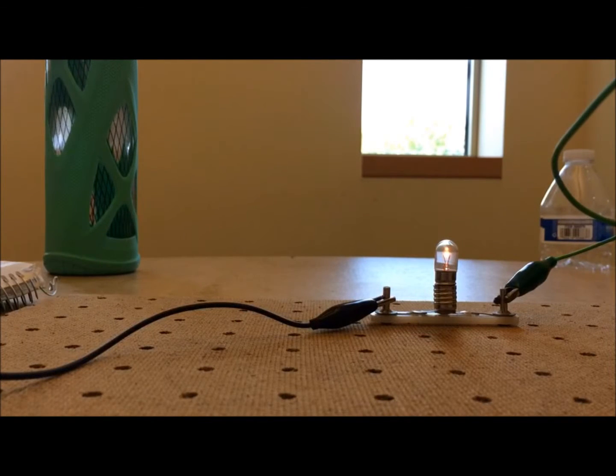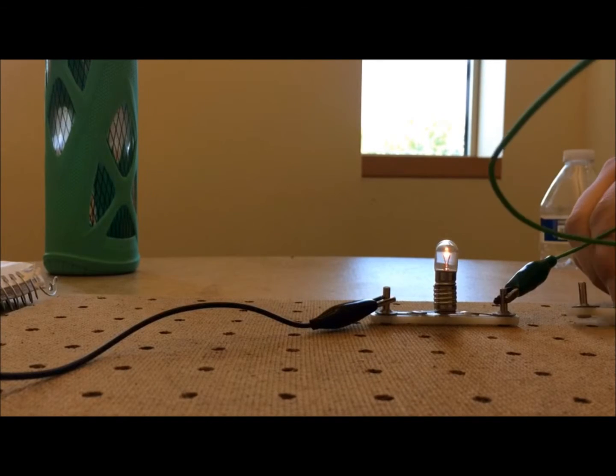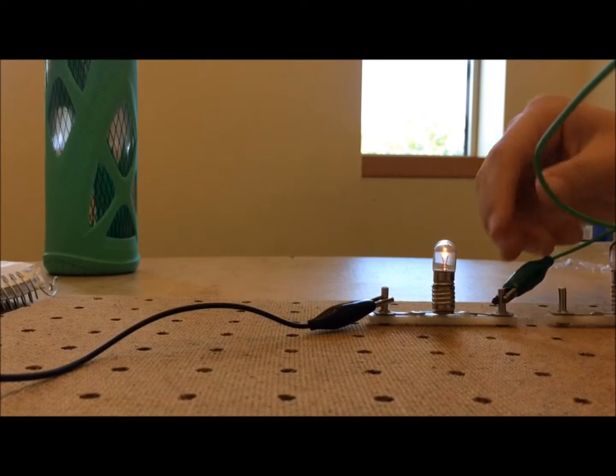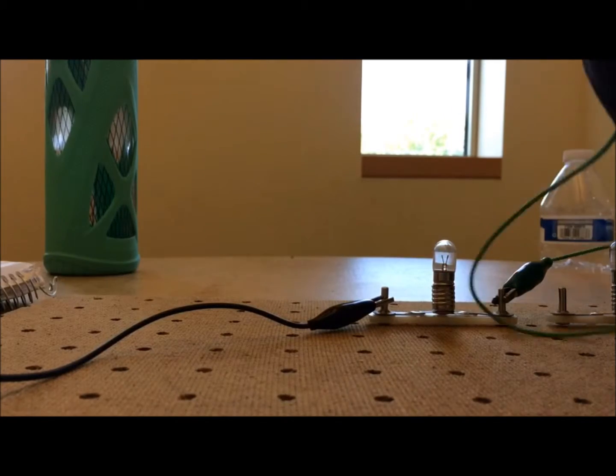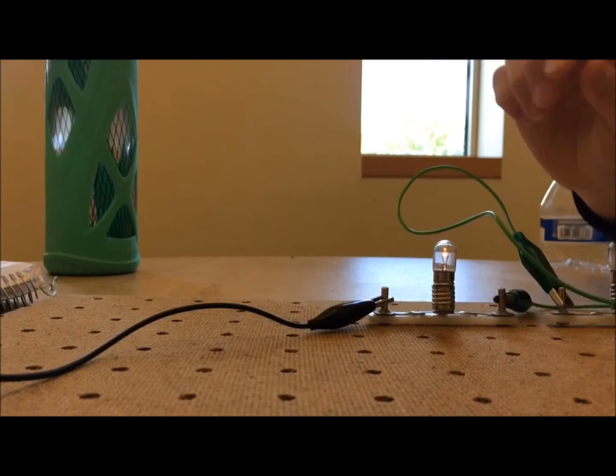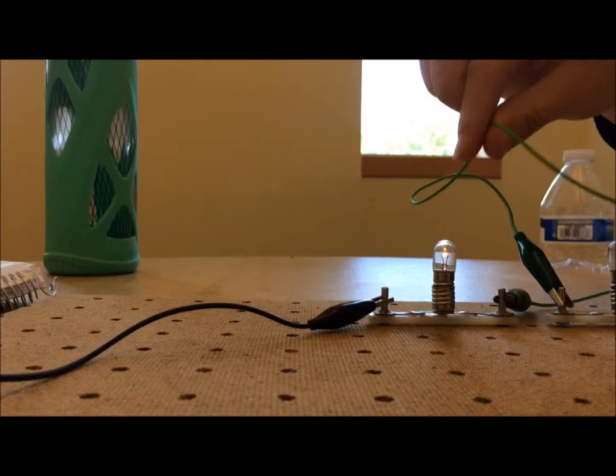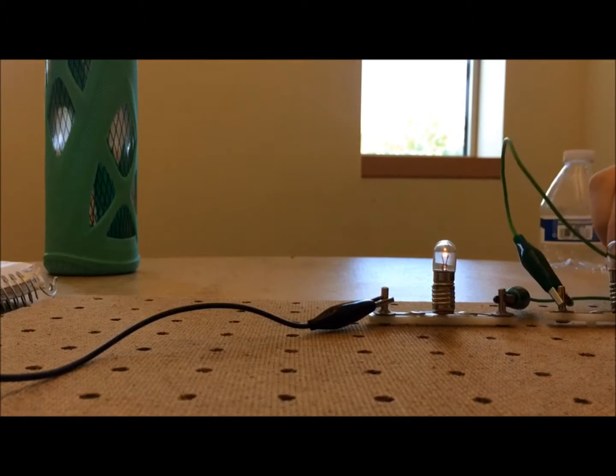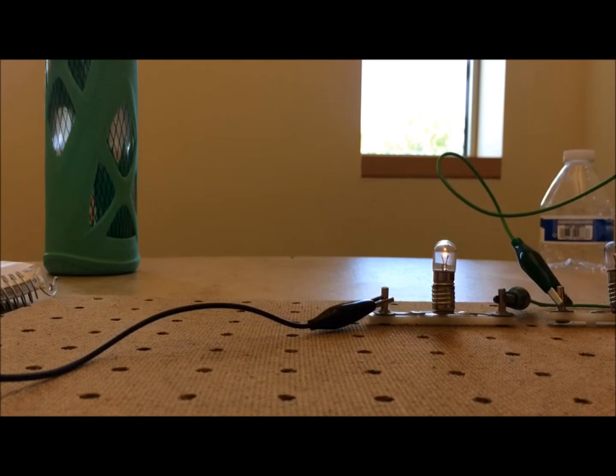The brightness of a bulb depends on the power dissipated by the bulb. Remember, power is given by any of the equations I squared times R, IV, or V squared over R. Okay, in a series, the current is not being shared, which means the light bulb gets the full current. But in a series, the voltage is being shared, which means as more light bulbs are added, the light becomes dimmer, and that's because the voltage is being shared.